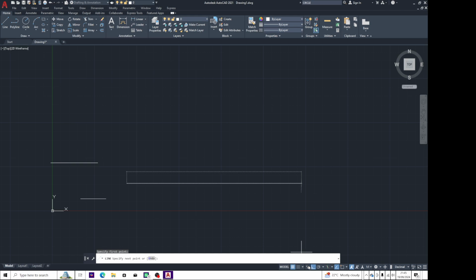If we deactivate it, then you will not see the units popping. So you should make sure that your dynamic input is always on.